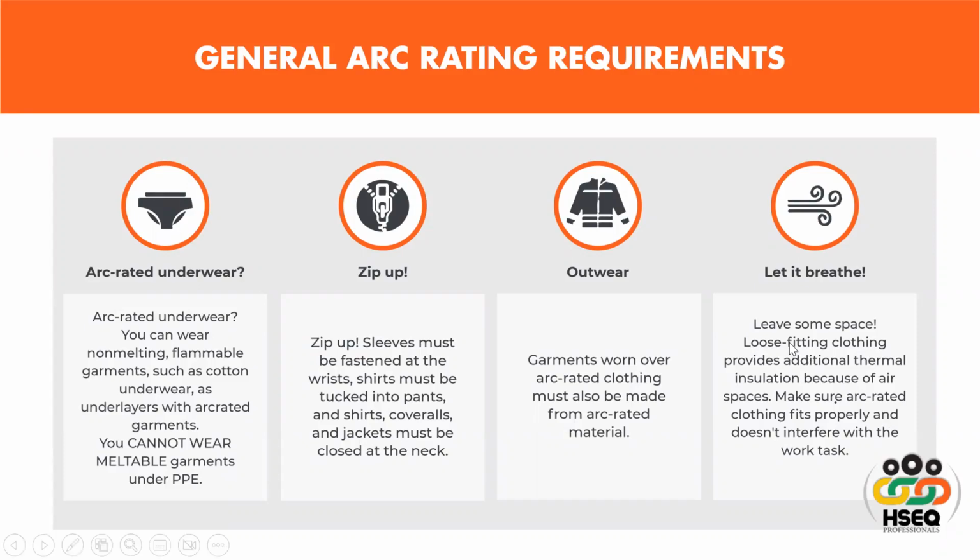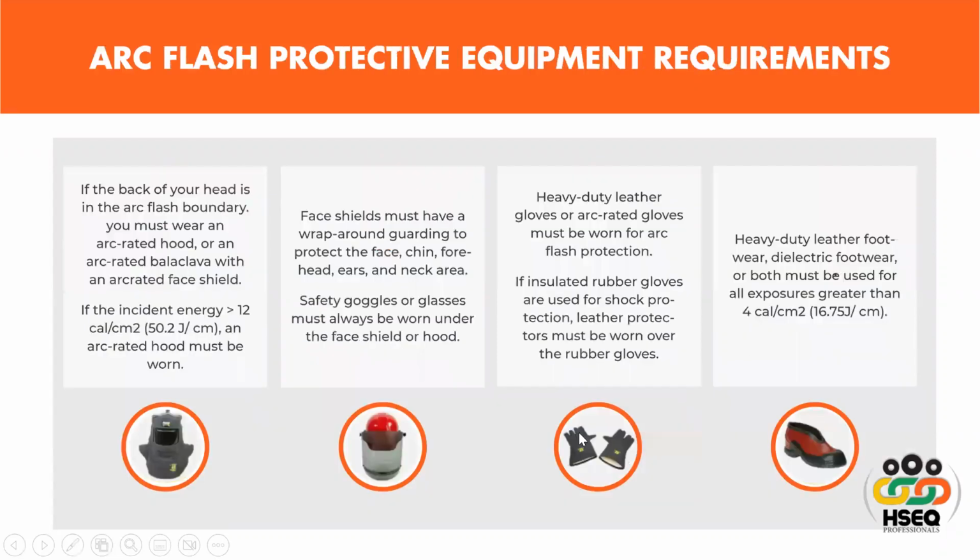So here it says leave some space. Loose fitting clothing provides additional thermal insulation because of air spaces. Make sure the arc rated clothing fits properly and does not interfere with the work task. Then if the back of your head is in the arc flash boundary, you must wear an arc rated hood or arc rated balaclava, which has a face shield attached to it.